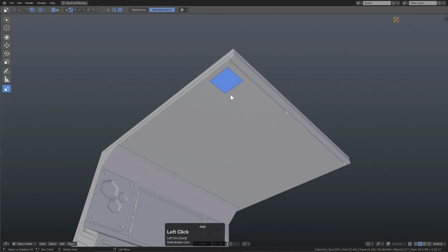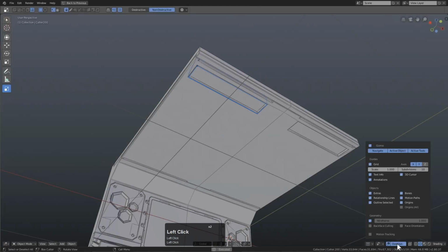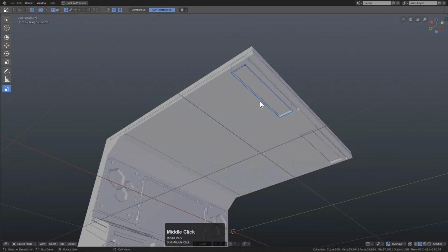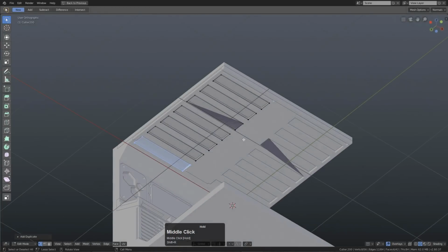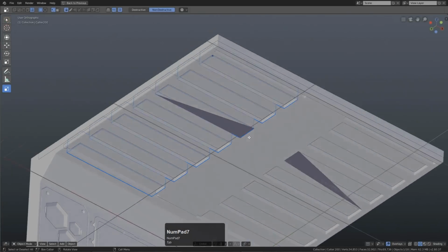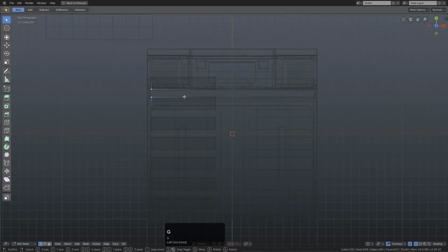One of the things I also like to do in Boxcutter is I'll draw a box, hold Shift, turn overlays off, turn off wireframes. I usually never turn off overlays because it affects gizmos. So Shift D, Y, Shift R, repeat it. I'll draw a couple of these in there. Let's look at it from top view. I'm just showing y'all some stuff I'm goofing off with as far as workflow, things I'm messing with to use whenever I come back with official Boxcutter content.